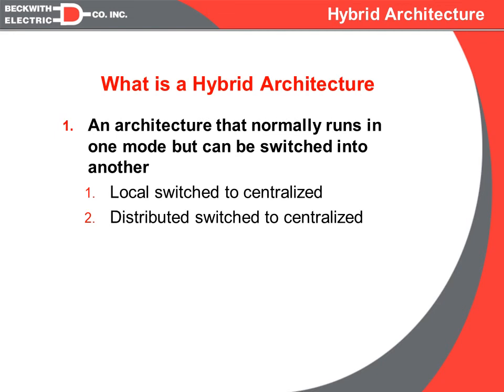So we could have the distributed substation automation systems running each substation, but then they can be feeding data back to the centralized SCADA. It can be running its own centralized IVVC, and again, if it sees benefit in taking over either one substation automation system from one substation or the entire system, it can then dictate commands through the substation automation systems to the end controls.